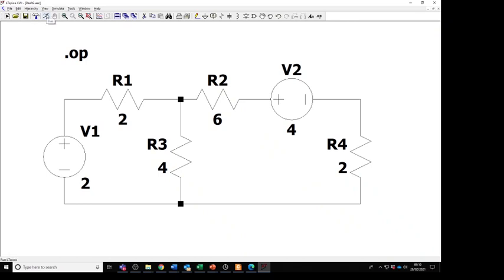Yeah, right. So I run that, and it should tell me, as Dan says, that it doesn't have a conduction path to ground. Let's see. Circuit does not have a conduction path to ground. Please flag a node as ground. Okay, and this comes down to the fact that voltages are relative, and at the moment there's no absolute voltage in here. All we know is that this one, for example, is 4 volts different from each end, but we don't have any absolute measurement for it to say that's 0.